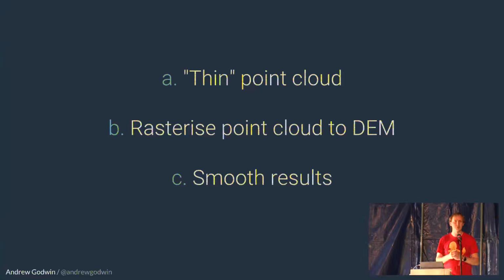And one problem I had was when I got data back from a LiDAR scan of London, it was when Crossrail was being dug initially, about 2014 or so. And the data was like, oh, there's loads of points that are minus 40 meters below sea level. And of course, it had seen the giant pit they'd put the TBMs in. And so rather than print a model with a big hole in it, I had to tell it to smooth it and bring it up to sea level. Like nothing should be below sea level. We'll ignore the giant hole in the ground for now.